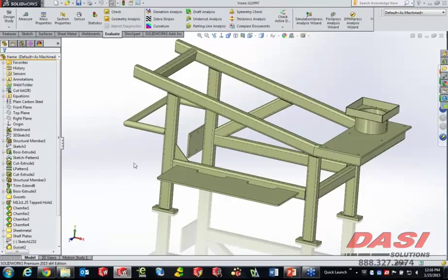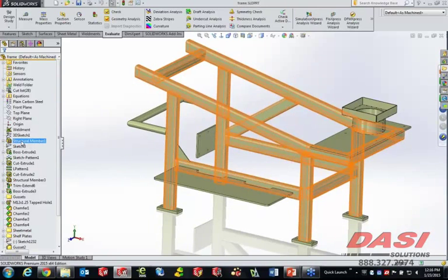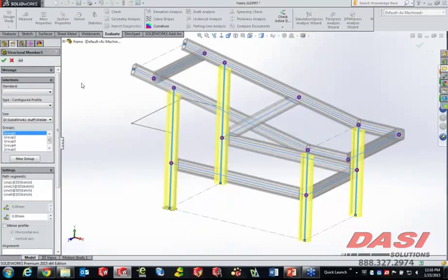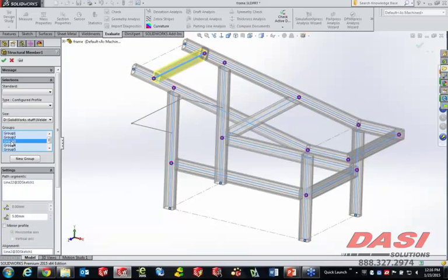welded structures. First thing I want to talk about is a little bit of the interface when it comes to the actual creation of the structural members and the groups. First of all, you can see what the groups are of the components on the screen a couple of different new ways. If you select the group, they highlight not only just the path down the middle of the components, but the actual bodies themselves highlight in yellow. You can also hover over the components on screen and you'll see what groups those components are part of. So really simple, I don't even have to scroll through it to see what groups each of these bodies happens to be a member of. So visually, that's a great improvement.